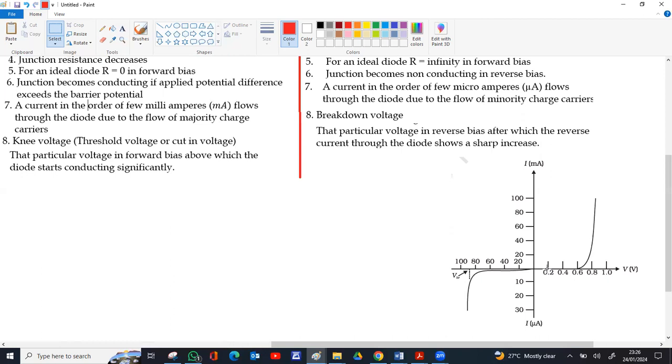In forward bias, at 0.2, 0.4, 0.5 and so on, it is not conducting. It starts from about 0.6 because electrons have thermal energy. But if you draw a straight line down to this, it will almost reach 0.7. That's the threshold voltage. So there is no current till this particular value, and a significant rise after 0.7. In reverse bias, the current is very small, microampere, and becomes almost constant as discussed, because the minority charge carriers are conducting and they are very, very few in number. So the current becomes saturated at its maximum.